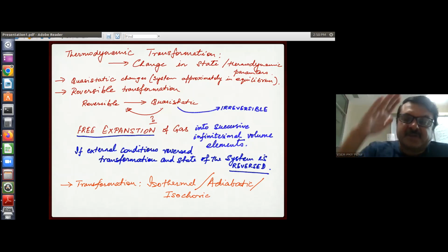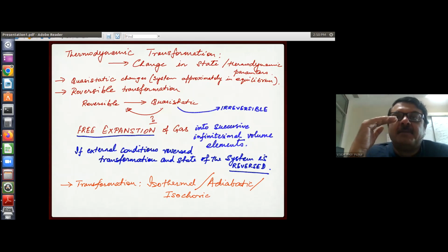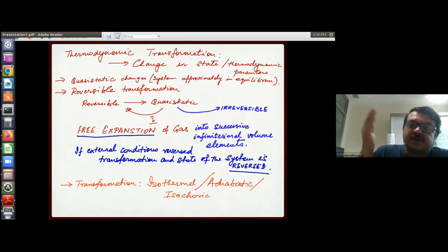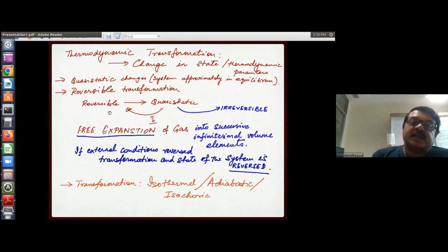Basically, suppose there's a glass jar and there's a piston on top and you're pushing it, so that the pressure increases, say. But if there's some dissipation, some friction of the piston with the walls of the jar, then some heat will be permanently lost. So even if you put it back from P1 dash to P1, it will be irreversible, right?